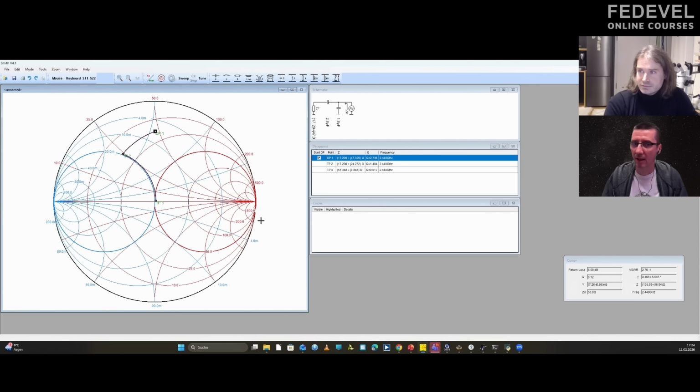Oh, this is nice. Okay, so again, I would like to add a little bit more information. We need to match 50 ohms because if the output, the trace, and the input are all matched, then it means there will be no reflection, and that's our goal. Exactly. And all the energy and power goes into the antenna. This is very important, because otherwise only a part of the power is in the antenna.